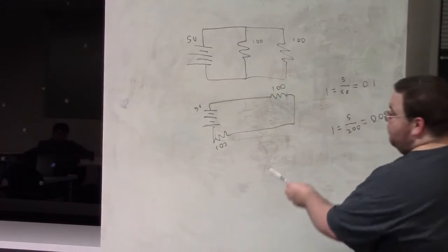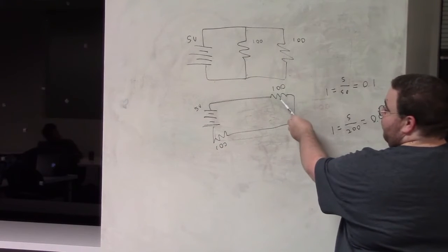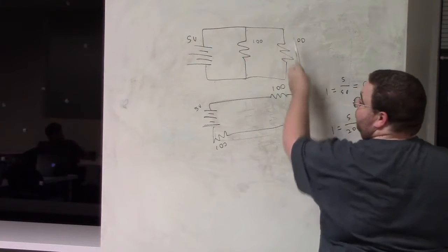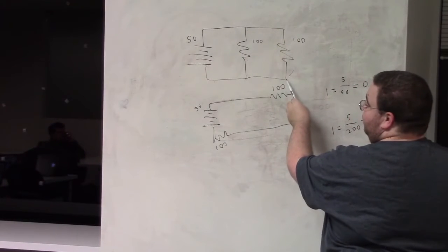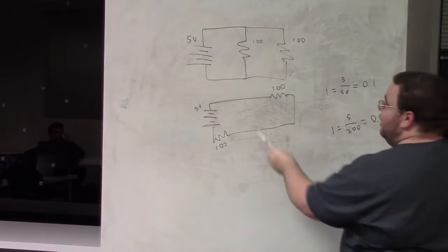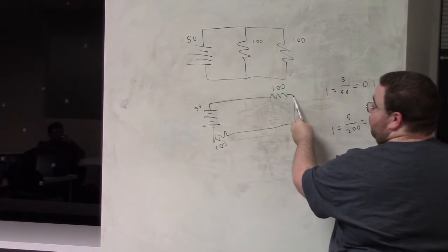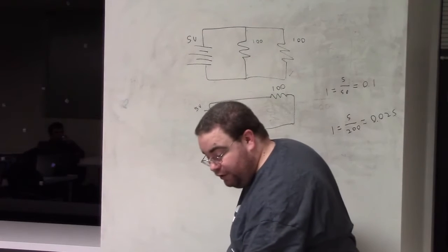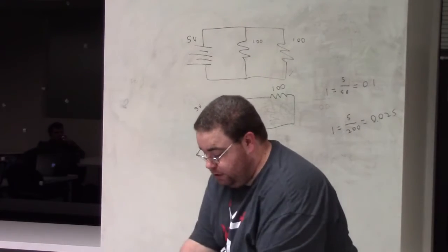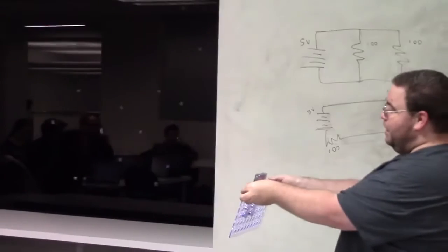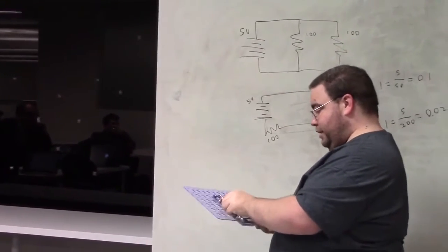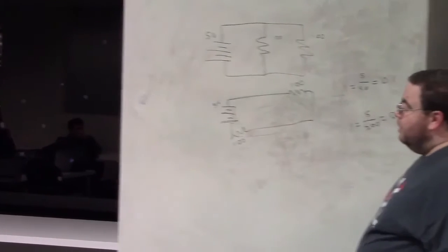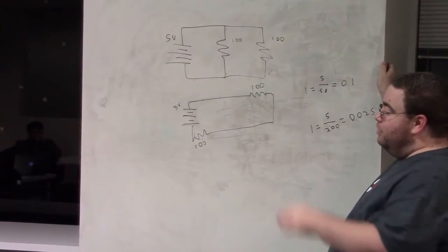Furthermore, a lot of that voltage is going to be eaten up by this first one. Remember that both of these guys are dropping from 5 to 0 volts. Everything's getting an equal amount of current, but this guy is dropping from 5 to 2.5, this guy's dropping from 2.5 to 0. It turns out that if you look at this, one is now brighter than the other one. See? And you can see the same thing. It's actually worse with LEDs. It actually makes more sense with LEDs. But that's why you do things in parallel instead of in series, is to increase the amount of current going to each thing.